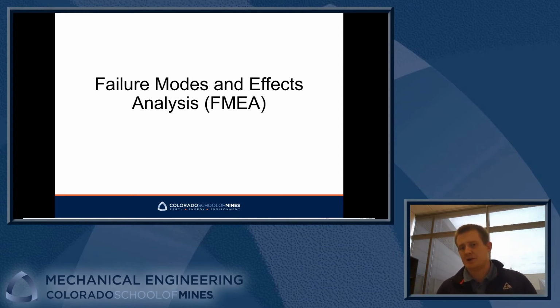Today, what we're talking about is the concept of how reliable this system is going to be. So we're going to do an analysis to figure out how our system could fail, predict those ways that we could fail, and figure out how likely it is that those failures could occur. Ultimately, you can use that information to design your system so that it will be more reliable, or to ensure how reliable it's going to be.